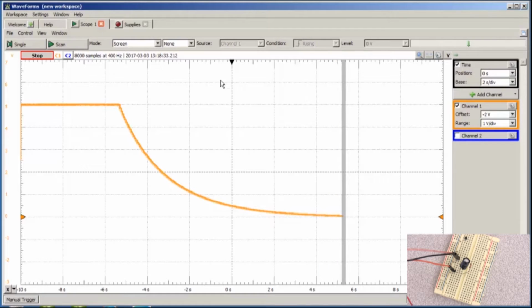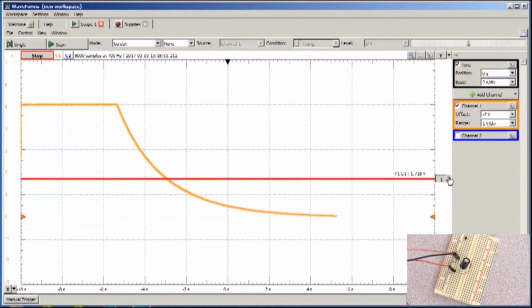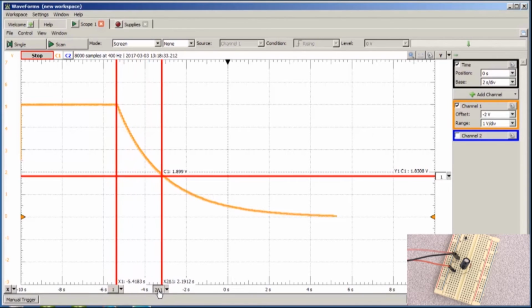Okay, I'm going to stop data acquisition, set up a cursor at my value of 1.84 volts, which is about 0.368 times 5. Now, measuring the elapsed time, there's about where I unplugged the red wire, and one time constant is about 2.3 seconds. So I don't quite meet my requirements with this combination. When thinking in terms of exponential functions and time constants, keep in mind their relationship with the governing equations for systems that store energy. Energy storage and transfer are really important to engineers, so we tend to see exponential functions a lot.